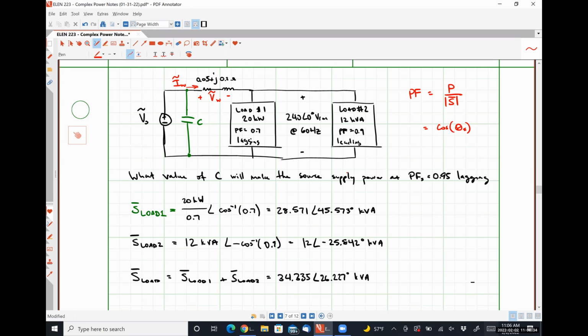We would find the current through each of the loads by first finding the voltage drop and their complex power, and that current is in series with this. Exactly right. So we don't have enough information to determine the voltage V_W because we don't know what our source voltage is. That information wasn't given, right? So Ian's suggestion is that all of this RMS phasor current, I_W, flows into the composite load formed by lumping loads 1 and 2 together, which we already found the complex power of.